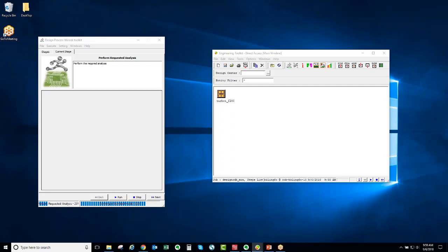You can, if you're doing HDI design or flex design, you can add on DRC functionality to validate those designs as well. If you're doing panelization in Valor, Mentor has actually spent quite a bit of effort lately in making the panelization process much easier within Valor. So you can do assembly panels and then full up panelization if your company requires doing that part of the design instead of farming it out.